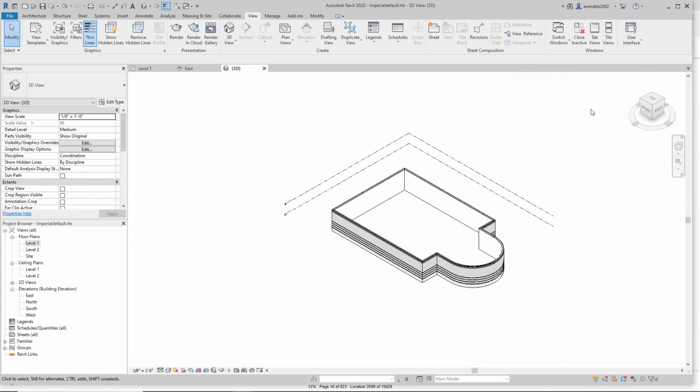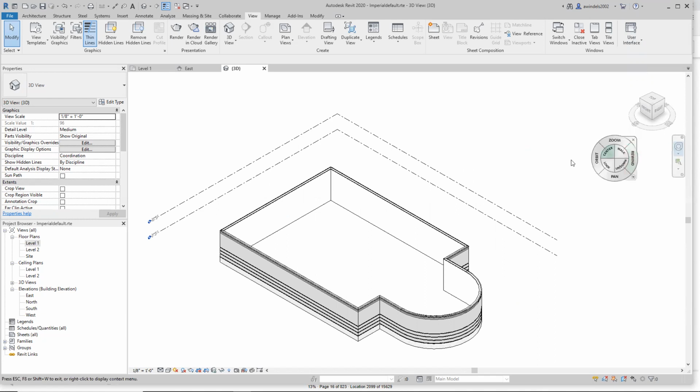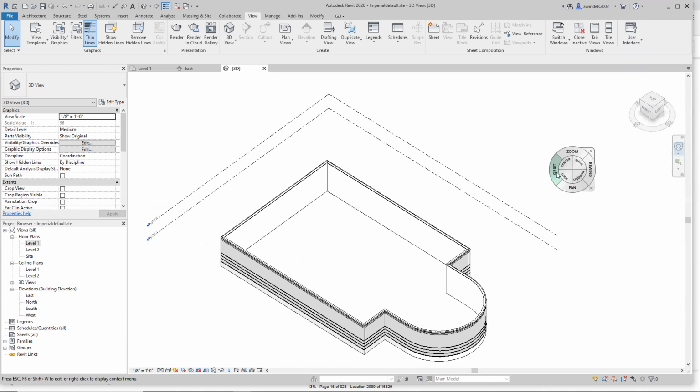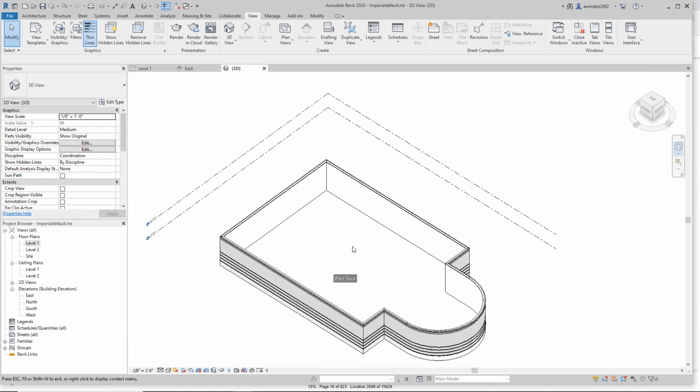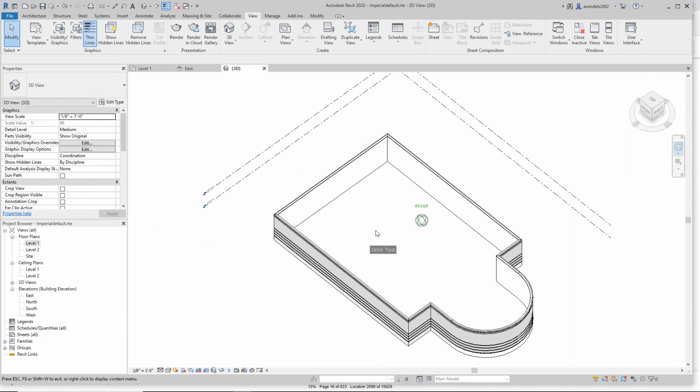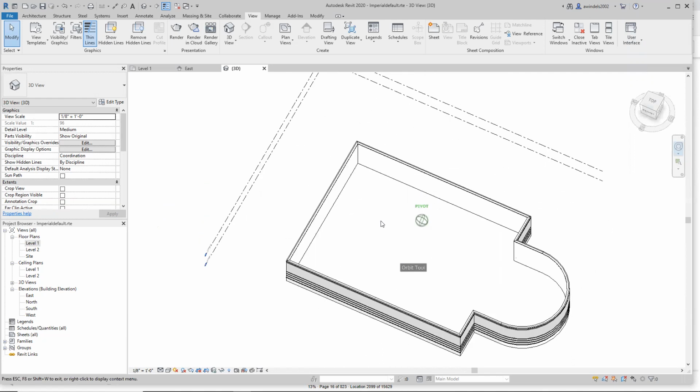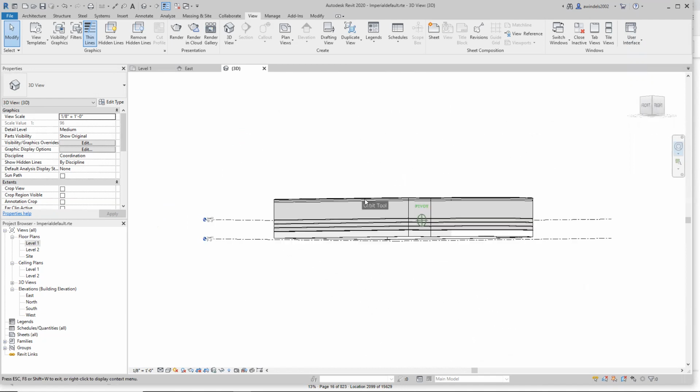You have different options show up on this bad boy, on the navigation wheel and the navigation bar. Select that. You have different 3D options to do walking and centering and moving around in a 3D manner. So orbit's on. Now you can repick where you pivot. Where you pivot's critical. So when you orbit, where you're pivoting is where you orbit around.